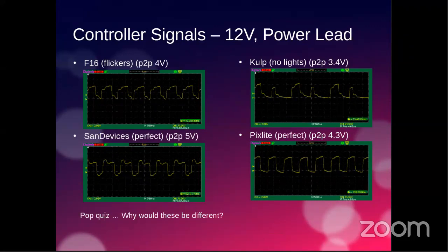It's to accommodate multiple protocols. Exactly. Yeah, maybe. Look, at the end of the day, it's not the protocol. It's actually the design of the pixel. The pixel's got a 33 ohm resistor on the input, and you're trying to match to it. I don't know. Obviously, Avitech has decided that 33 ohms is the way to go, and they support basically as many different types of pixels as Dave supports.